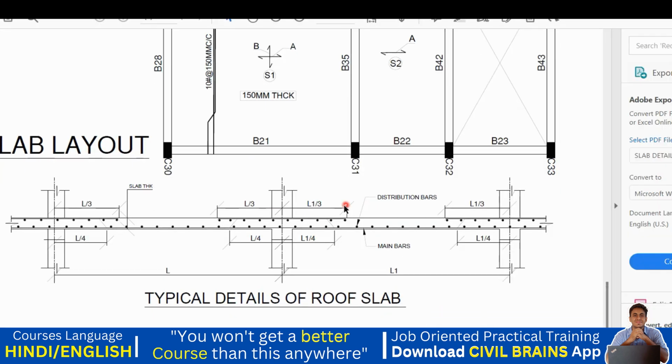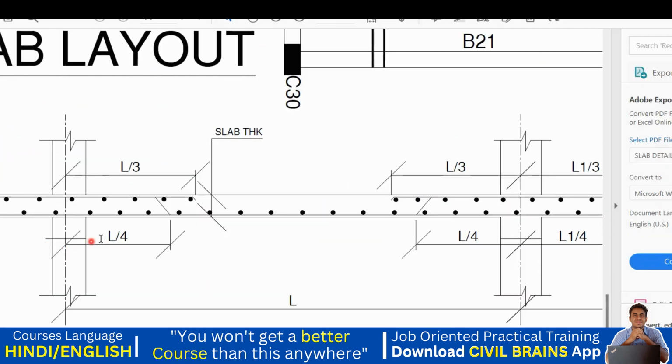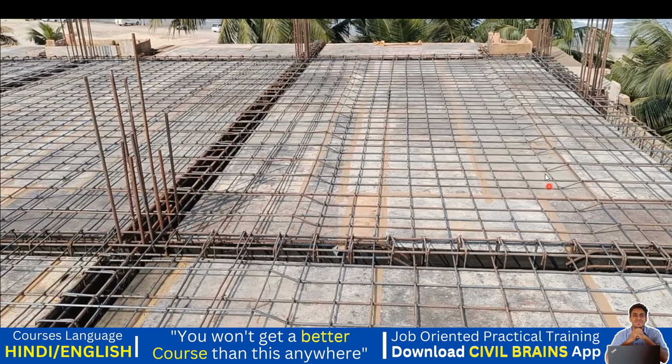And that is why practically when we detail anything, this is a kind of detailing we try to give. We can see the crank bar given here, right? So this is my crank bar, you give it an L by 4 distance. Now one more point we need to understand. It has been found that whatever negative bending moment happens, it will happen at a distance of L by 4 from the support.